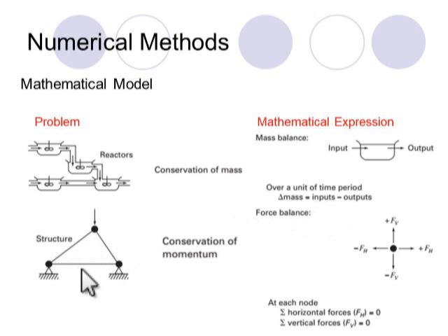Basically, we have a truss system here which is fixed to the wall with anchors, okay, and there exists an external force. Now in this case, conservation of momentum or conservation of mass is applied, because we know that at each junction the sum of the forces has to be equal to 0 for static equilibrium. So this means that the sum of the horizontal forces has to be equal to 0, and the sum of the vertical forces has to be equal to 0 for this configuration.